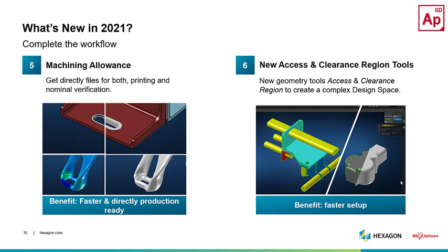Anybody that's ever done that realizes the value of this tool, because that means that nothing is going to get in the way of the screwdriver in order to turn in that screw or the drill bit or anything else, because you can create those nice quick clearance regions inside of your optimization, and then nothing's going to just optimize and create a path of metal right in front of a fastener hole or something like that.